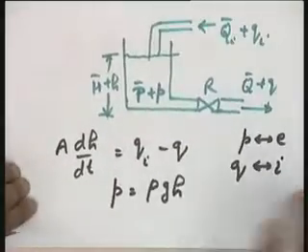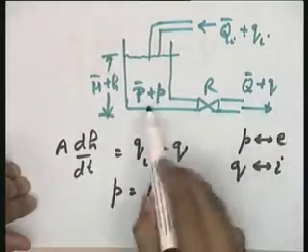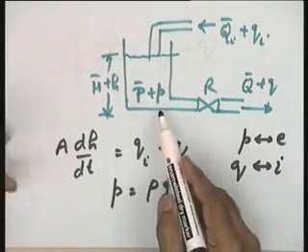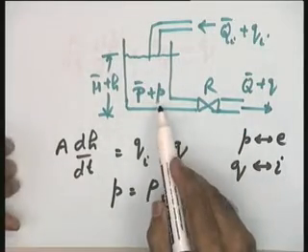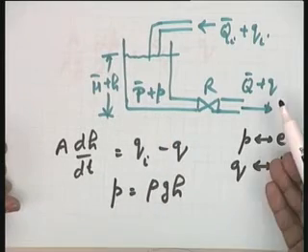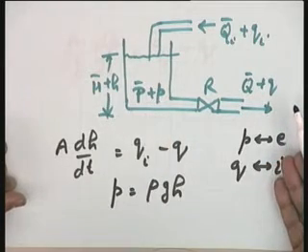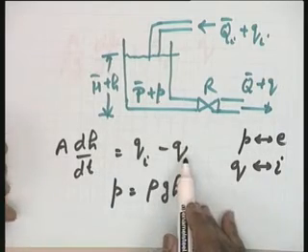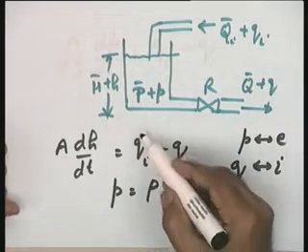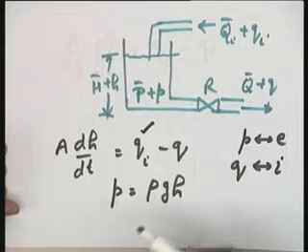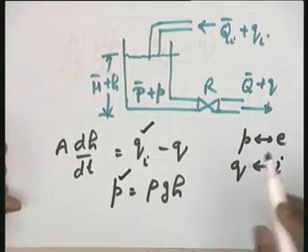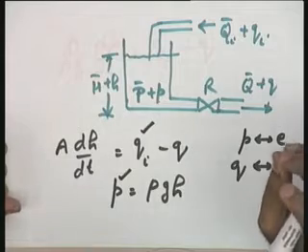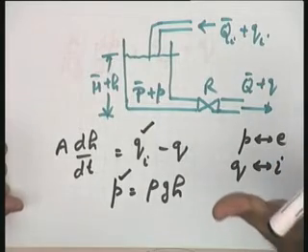Please see that the pressure and q, these are not independent variables. So, you see, actually they are controlled variables. If I am controlling pressure P, I am controlling the flow Q as well. So, I really want to relate P and Q so that in my mathematical model I have only the input variable Qi and the output variable P. So, it means this Q, the output flow or the outflow should also be eliminated. I need your help here.